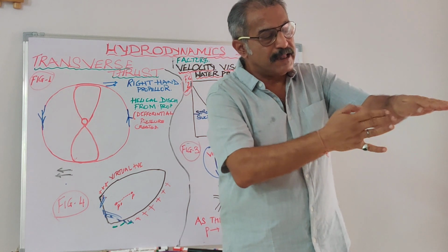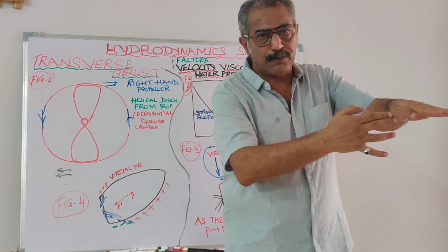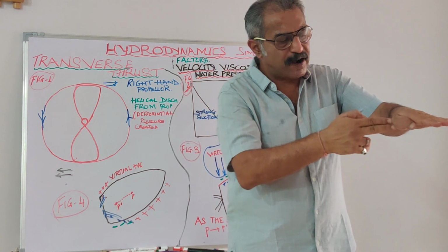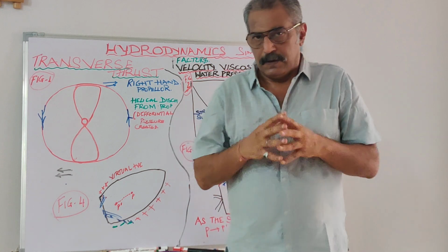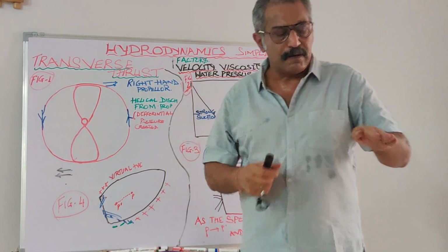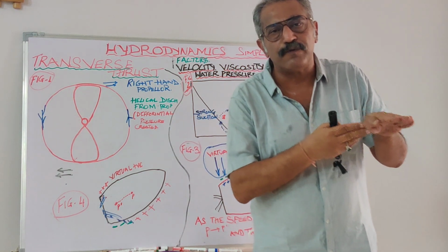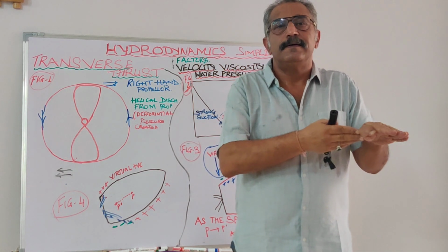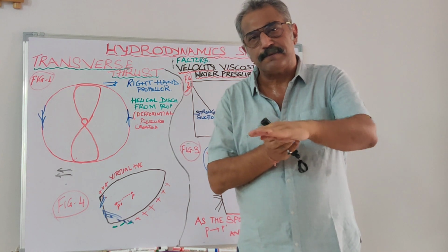It's something like this: I've connected a tug here and I'm asking the tug to push. With whatever is the fulcrum, she's swinging to starboard. So the vacuum which is created on the starboard side is acting as a kind of virtual tug push, which is facilitating the vessel to cant to starboard.